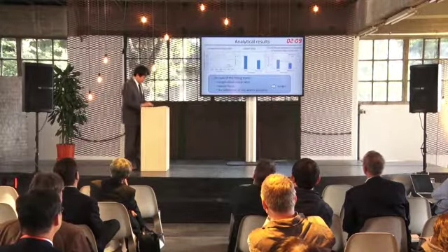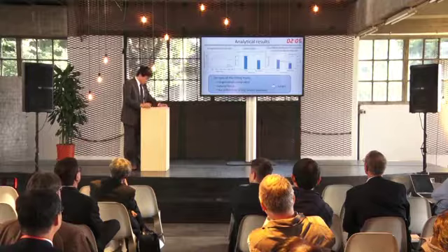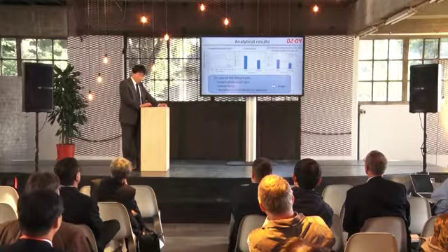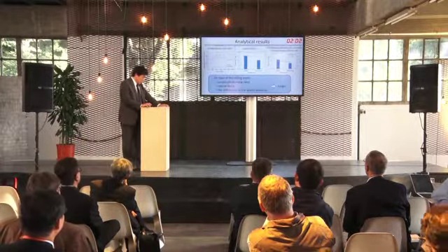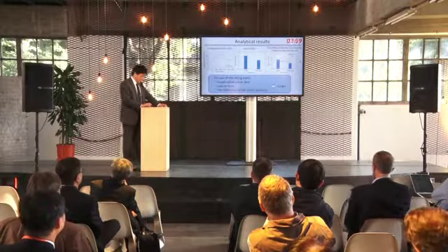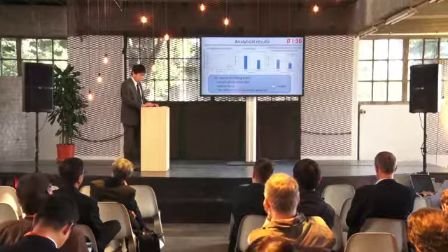As for the tilting train, the longitudinal creep ratio is larger than for the non-tilting train. It is the result of the difference between the diameters at high and low rails due to the lateral force. Especially the difference between the diameters at high and low rails of the tilting train affects the longitudinal creep ratio more than that of the non-tilting train because of the difference of the wheel diameter of both trains.